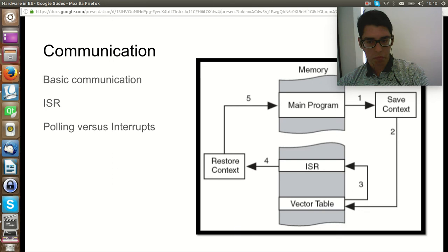Polling is within a loop, which is reading the status of a function all the time. Interrupts are an asynchronous electrical signal from external and internal peripherals. Interrupts are dispatched by the ISR, and ISR stands for Interrupt Service Routine. This means that the processor, after processing the current work, sets aside the current work before the processor returns to the work that has the interrupt.